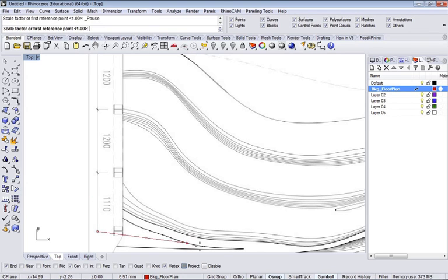And the other thing I'm going to do is turn on ortho down at the bottom. I'm just going down here to the bottom, clicking on that to make sure that I get these straight lines. So it makes it a little easier. Then I'm going to line this thing up. And then I'm just going to type in, so that gives me my 2 reference points, and now it's asking me where my last one is. So I'm just going to type in now the dimension, which is 1100.